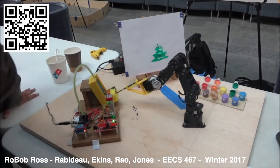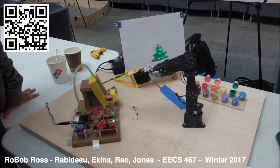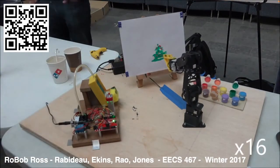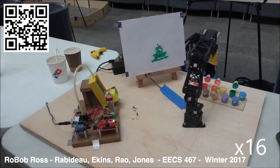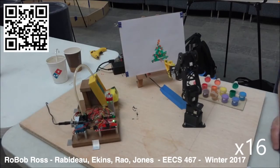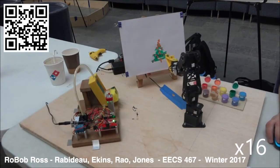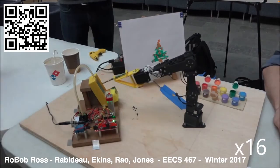I believe the input to this robot was a desired painting in the form of an image. Based on the image, it could break the image down into a set of paints to be applied. From there, it could define the desired end effector position, which could be solved using inverse kinematics for the joint angles. And then once again, it could plan a trajectory using those joint angles as set points.